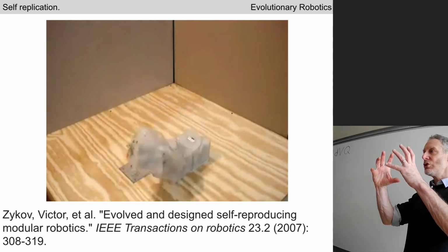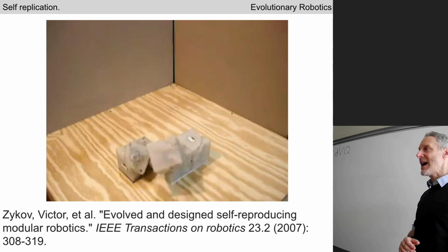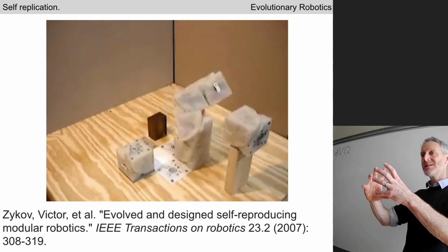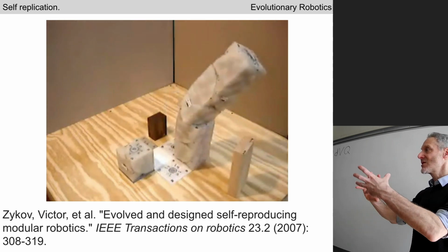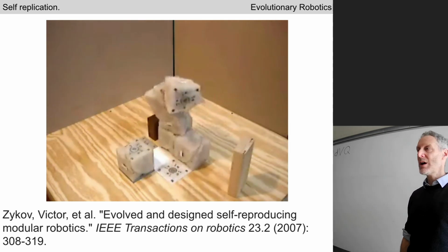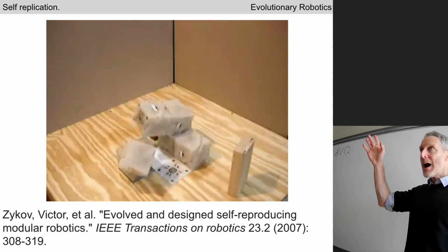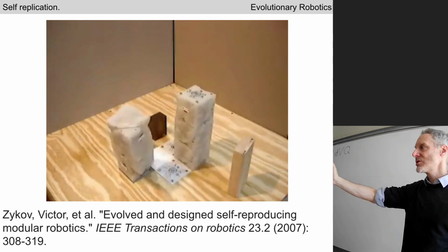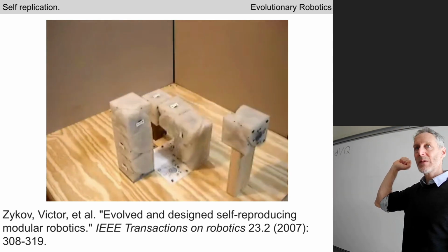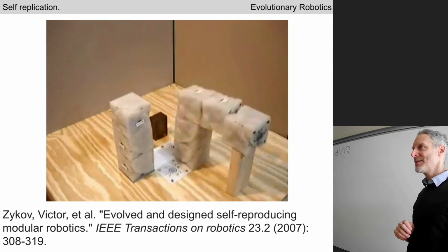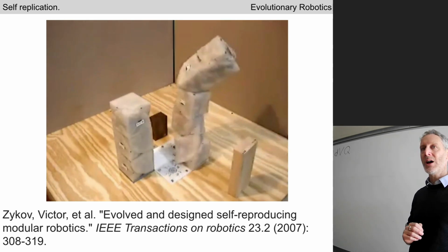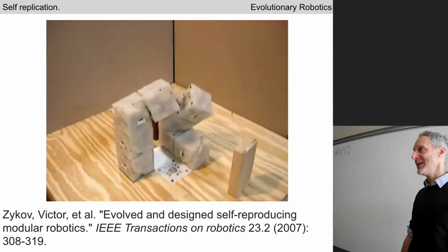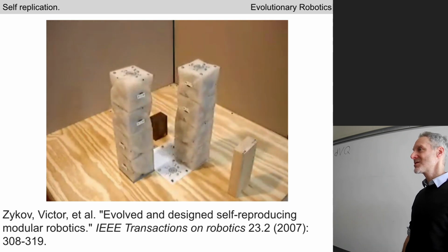You'll notice that these cubes rotate about their grand diagonal. There's a diagonal cut through the cube, and there is one motor inside each cube that rotates the 2 halves of the cube relative to one another. And if the upper half of the cube has some cubes attached to it, that whole arm rotates through 3-dimensional space. So kind of an odd robot. We haven't seen anything like this before, but you can see how a lot of these mechanical design decisions were made to facilitate the one and only thing this robot is designed to do, which is self-replicate.